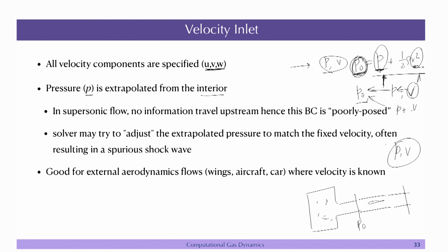This is one reason, there are multiple reasons. One thing is that we will talk about something called Riemann invariants. Okay. So, that is a combination of P and V. Okay, those are Riemann invariants. P basically, V and A, the speed of sound and the velocity. Okay, but speed of sound in turn depends on the pressure. Now, Riemann invariant, what it says, if you look at the compressible literature, which we will discuss shortly, is that you have some characteristic coming in and some characteristic going out. Okay. Something is coming from inside to out, something is coming from outside to in, right.